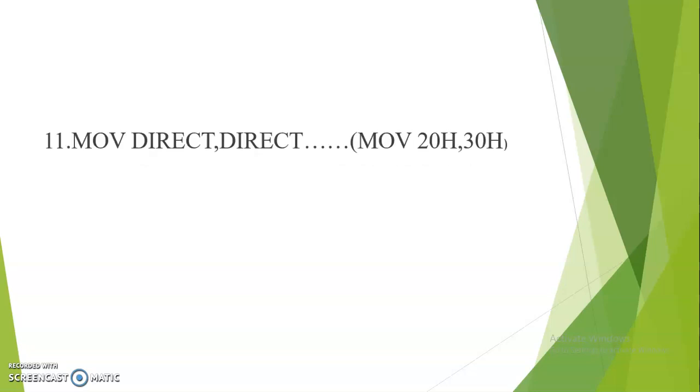Now we will see the next example, MOV direct, direct: MOV 20H, 30H. What will this do? This instruction will copy the contents of the source direct address to the destination direct address. So 30H is the address, the location. There are some contents, say suppose X. Those X contents will be copied to a location whose address is 20H, and the contents will be copied.